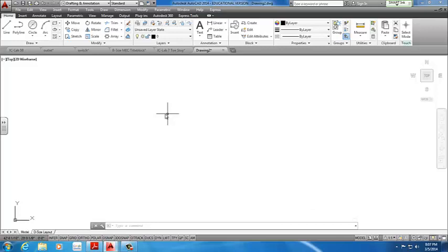the cleat. So we're gonna start drawing with a line, and preferably keep close to the x and y coordinates, the 0, 0. That way, your objects aren't far away apart from each other. We're gonna draw a line across, making sure our ortho is on. That's gonna be 4 inches across.